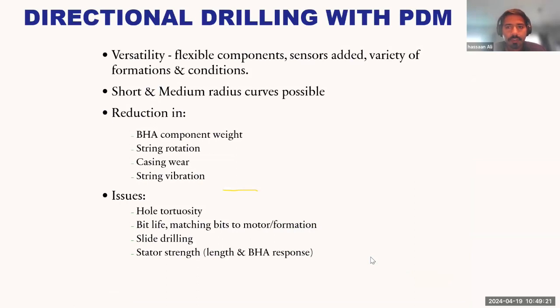So with the advent of positive displacement motors, they have proven themselves to be a very valuable part of directional drilling. They are more commonly used now because of the reliability and high rate of penetration that they offer. With the PDMs, you can integrate them with the sensors, MWD and LWD tools, and it can help you evaluate the formation in real time, as well as drill the formation at a much higher rate. They are very suitable for different types of formation and conditions, and I see them being used more commonly now.